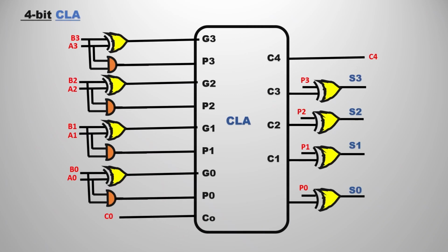The construction of the 4-bit CLA has just started now. Up to now, what we have seen is just the carry. We took the input lines as C0, P0, G0, P1. So these are the things that we did not see inside the full circuit, that is the CLA. That is the simple thing I have represented, all the circuit that we have seen up to now. So this is the actual circuit diagram of the 4-bit CLA.